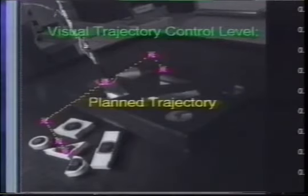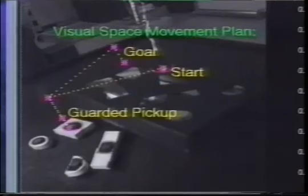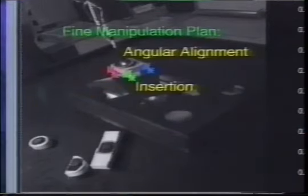This is how the task looks like on the trajectory planning level. Planned trajectories are compared with the actual movement, and the model is updated based on any discrepancy. When switching modes, the fine manipulation model is bootstrapped from the simpler transportation model. Trajectories are planned in stereo camera space using local visual models defined by the lines and corners found in the scene. These visual models are approximately Cartesian and thus define above and sideways.